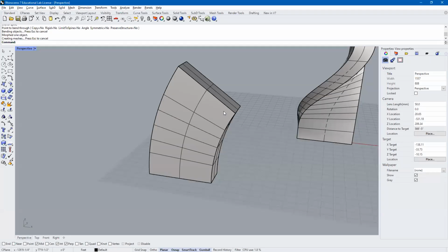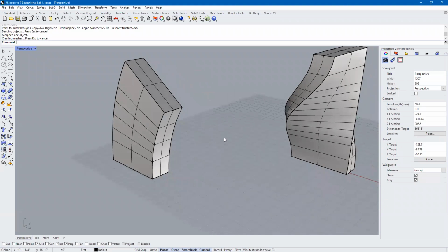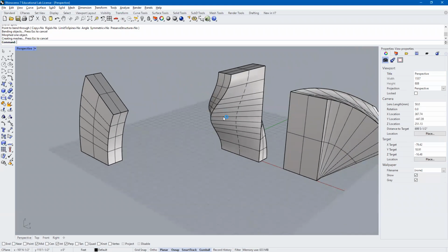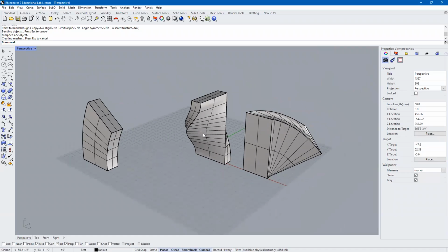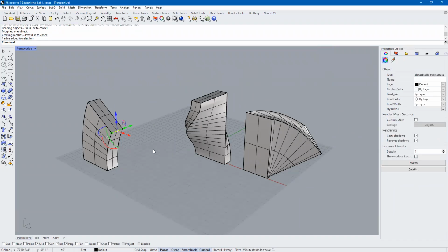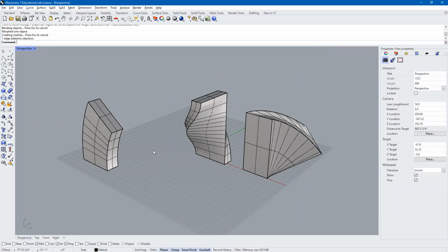So it's like taking a building and just giving it a bend in one direction is all, which is different than the twist command that you have there. And again, achieving different results. I would not be able to do this by just simply selecting the edges and trying to move those edges down. Using these two different commands makes it go a little quicker. So that's what I wanted to share out with all of you. Practice them, see if you like them or not. I want you to just know that they are there.